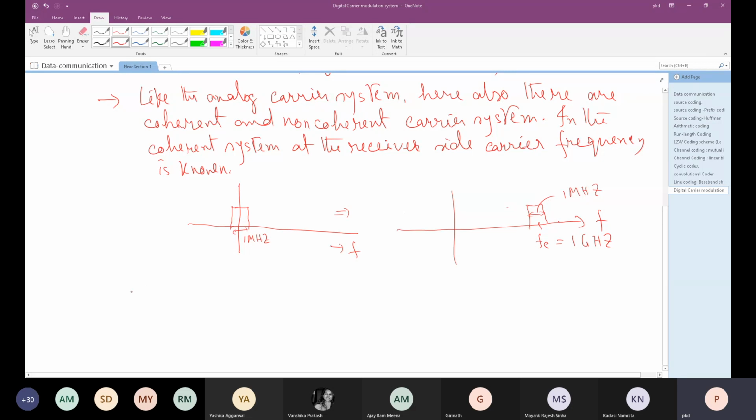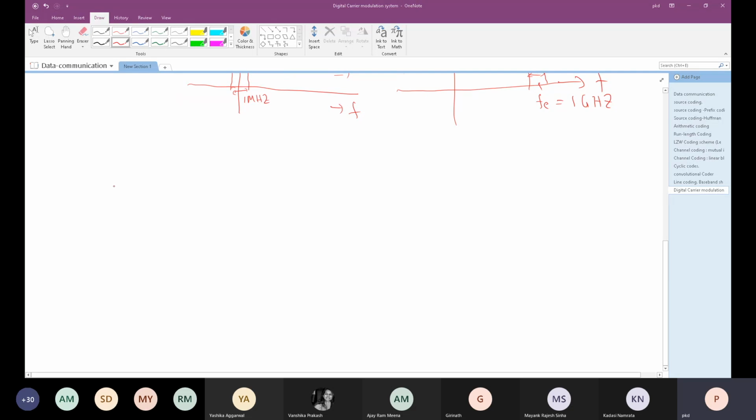However, in case of coherent, because we are expressing in terms of a known frequency, usually the analysis can be done in terms of a carrier frequency and its projections onto various phases. In general, theta can have a frequency shift or it can have a phase shift. That can be projected in terms of an angle change in a multi-dimensional space. So we shall introduce a little bit of signal space analysis to analyze digital carrier signals.